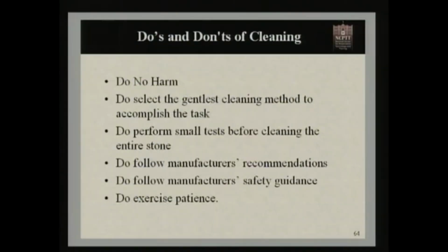All right, so we've sort of talked about the don'ts. Let's talk a little bit about the do's. You want to do no harm. You want to select the gentlest cleaning method to accomplish the task. And this goes back to that question we asked ourselves earlier: why are we cleaning the stone? Was it just to remove some soiling? Maybe just water will work. Was it to remove biological growth? Maybe we want to look at something with biocide. So keep that in mind.